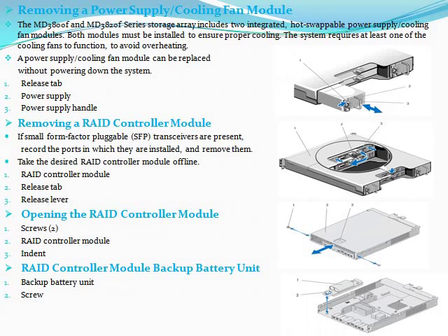If the fiber optic cables are present, it may be necessary to remove the RAID controller module using the two release levers. Opening the release lever makes it easier to press down the fiber optic cable retainer. If the system is still running, do not disturb the second RAID controller module. Pull down the retainer, then grab the release lever and pull it away from the chassis.